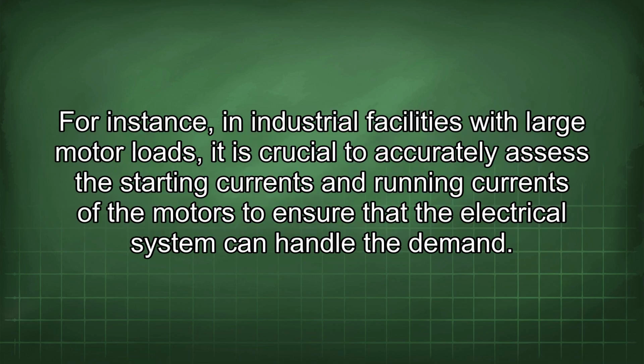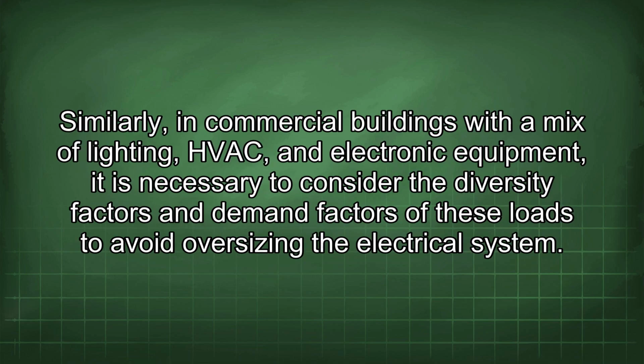For instance, in industrial facilities with large motor loads, it is crucial to accurately assess the starting currents and running currents of the motors to ensure that the electrical system can handle the demand. Similarly, in commercial buildings with a mix of lighting, HVAC, and electronic equipment, it is necessary to consider the diversity factors and demand factors of these loads to avoid oversizing the electrical system.